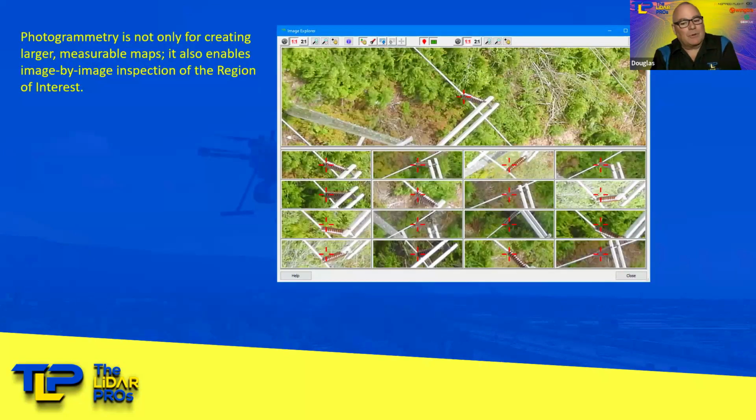As we're flying our mission, we're capturing all these individual images with our drone that are going to be assembled into a larger orthomosaic map, or sometimes into a 3D model. We can still use each of these individual pictures that we're capturing for points of inspection. So if we need to go see something at full resolution, and in Pix4D this is going to be found on the right-hand side of your screen, bear in mind we can always go and look in deep detail at what's happening in the scene with the actual photograph, as opposed to just simply looking at the larger orthomosaic that we've mentioned.